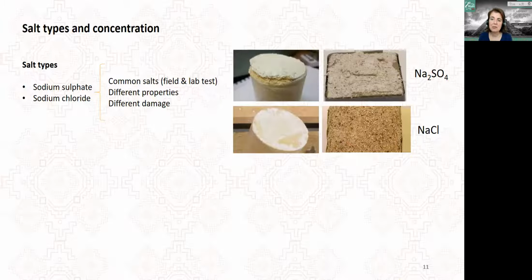Regarding the salts, we decided to use single salts in order to limit the complexity of the test. Besides, according to the literature review we did, salt mixtures are often less damaging than single salts. So despite the fact that we are aware that in the field more often salt mixtures are present instead of single salt, because of this reason we decided to use single salt, and we think it's representative enough. Regarding the type of salt, we decided to use two salts, sodium sulfate and sodium chloride, and to develop the procedures for these two salts.